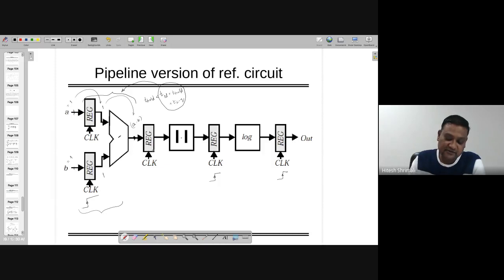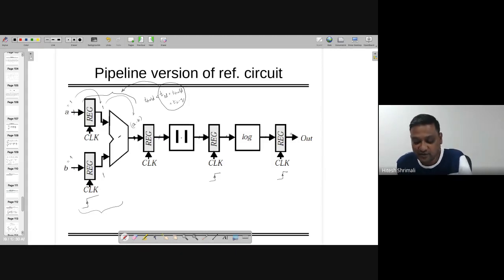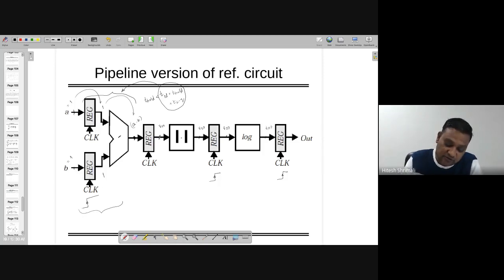In that case, this is not going to take the faulty input, or you can say that the output of each one of them might be 0 if you have made it in such a way that they are 0. Sometimes some people are also keeping it at VDD, meaning they have used a register which is going to precharge the value, right? Like we did in the sense amplifier based register.